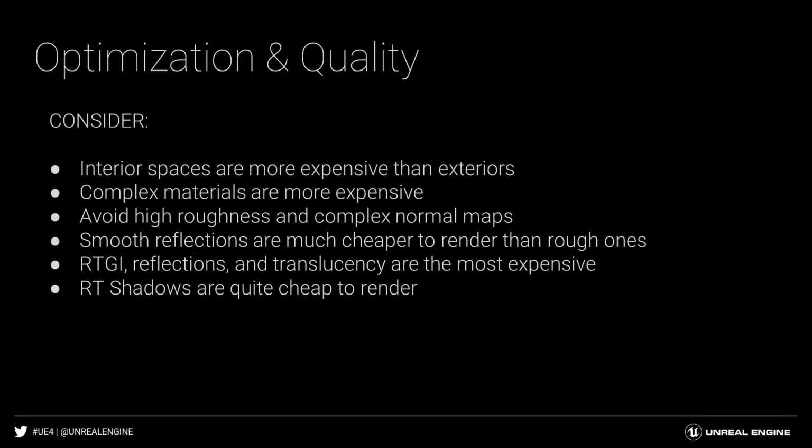Keep in mind that Unreal is a hybrid ray tracing solution, so you can pick and choose the effects that have the most visual impact while having the least effect on performance. That's going to depend from scene to scene. If you have a scene with a lot of reflective objects, you're going to want to use real-time ray traced reflections. Likewise, if you have a lot of translucent objects, you'll probably need to use that. And in real-time GI, remember, you have two options. You can go with brute force, which is more accurate but much slower, or you can go with the final gather solution, which does a really good job of approximating the full ray traced algorithm.